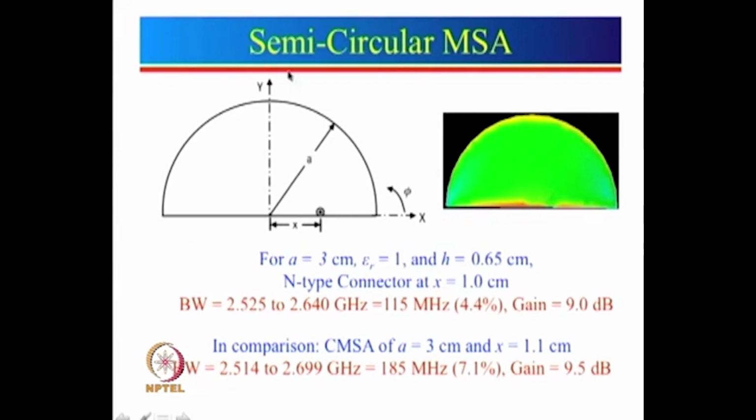So in fact, just to mention, later on when we talk about a broadband technique, we will show you where we had replaced a circle with two semicircles which are gap coupled, and we got much better bandwidth in comparison with the circular patch. So for that you have to wait for some time.